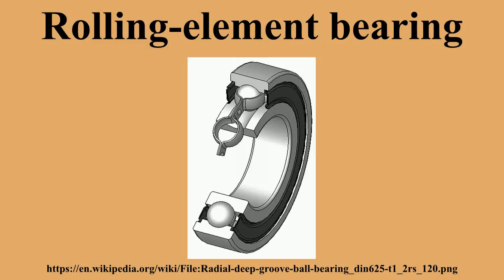Roller bearings. Cylindrical roller. Common roller bearings use cylinders of slightly greater length than diameter. Roller bearings typically have higher load capacity than ball bearings, but a lower capacity and higher friction under loads perpendicular to the primary supported direction. If the inner and outer races are misaligned, the bearing capacity often drops quickly compared to either a ball bearing or a spherical roller bearing. Roller bearings are the earliest known type of rolling element bearing, dating back to at least 40 BC.